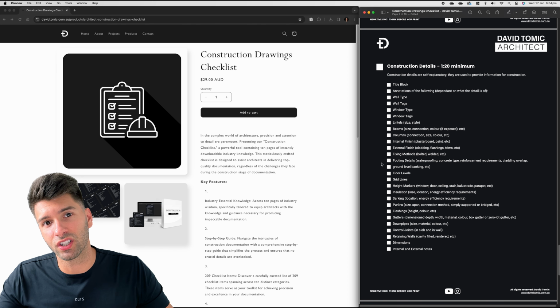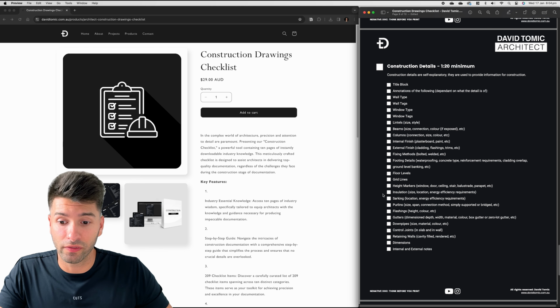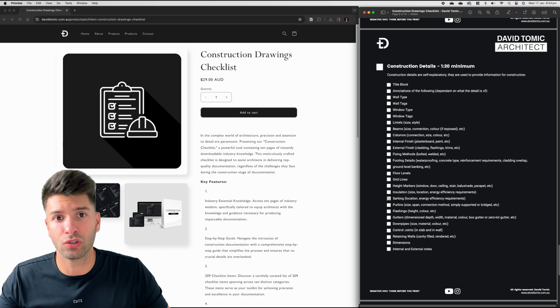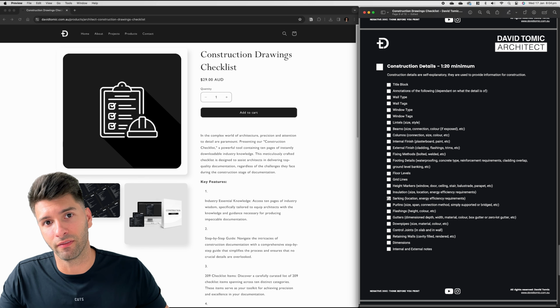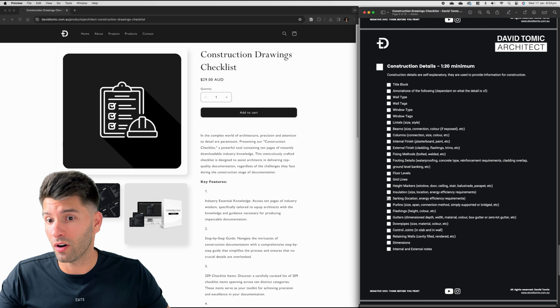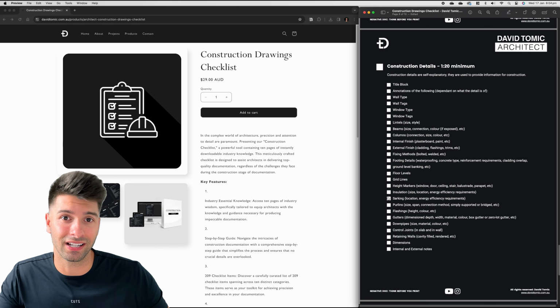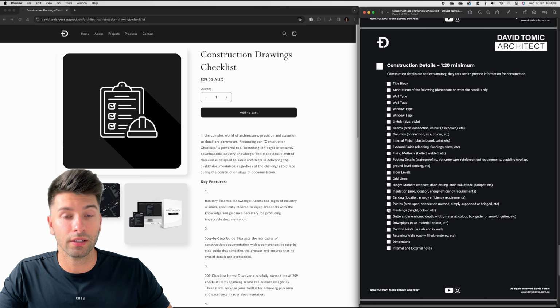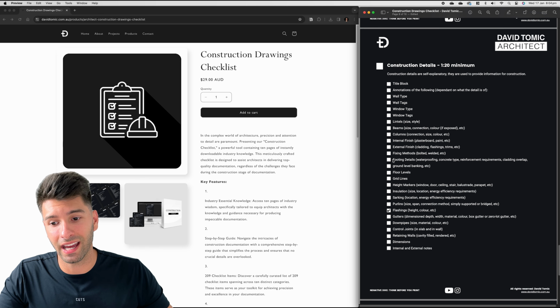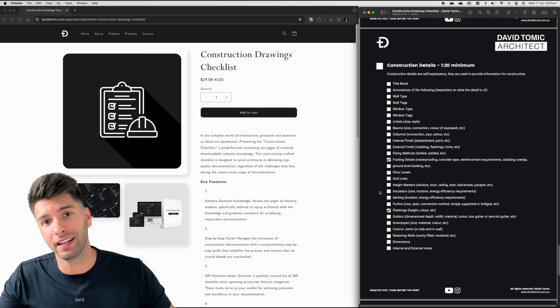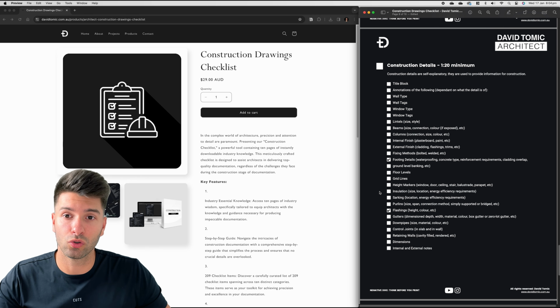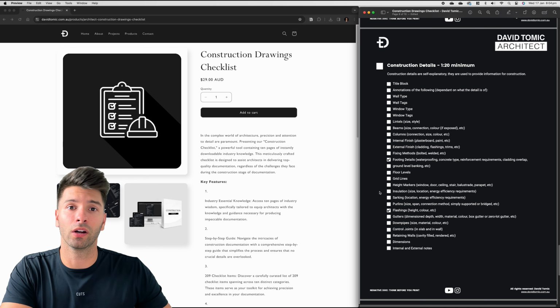When we're talking about construction details, we're talking about the finer details you can't see at a 1 to 50. So for instance, sarking. Sarking is so thin most of the time that you'll just see it as a blank line on a massive 1 to 50 section. Whereas at a 1 to 5 or 1 to 20, you're going to be able to actually articulate this a lot better. Same goes with our flashings, of course, and our waterproofing details for our footing details. All of these things can be articulated in construction details so much easier than they can be anywhere else in the documentation package.